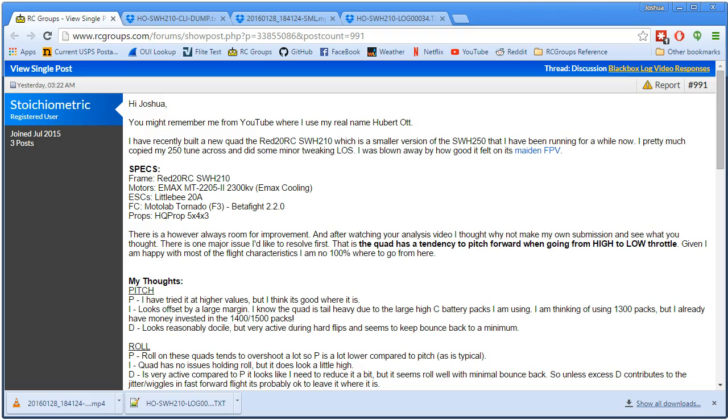There are people who make their living discussing the things that propellers do to air, and I am not even remotely one of them. But we do know that when a copter is in forward flight, the back props are interacting with the prop wash from the front props. It's plausible that there is a throttle-dependent effect that is resulting in a pitch back moment, which is causing the rear motors to make less thrust effectively.